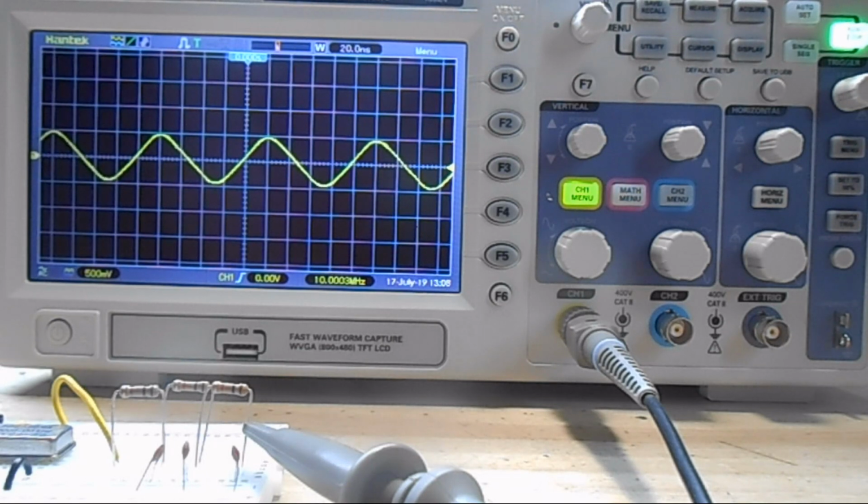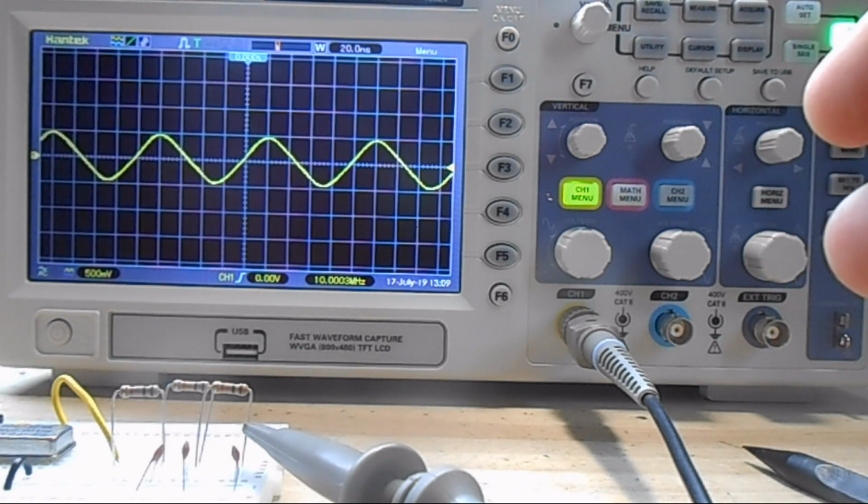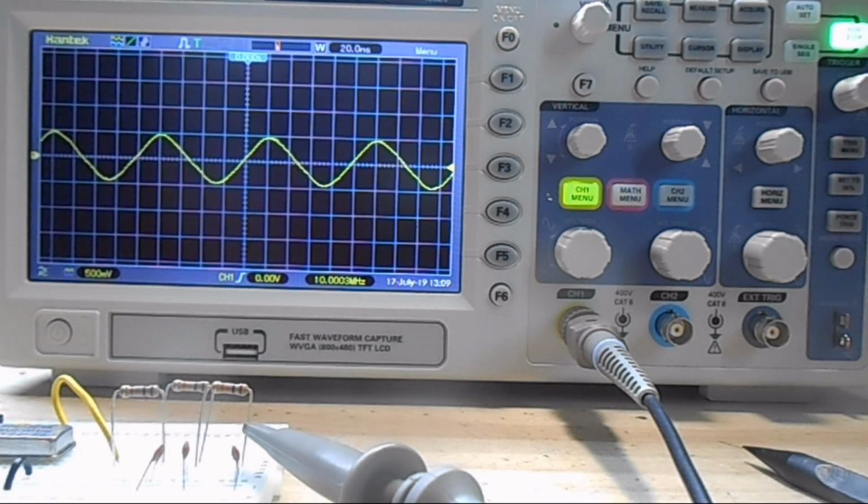Now we also have trigger sweep, and that's what we have over here. You see where we have our run, stop, and our single sequence. We have an auto trigger sweep, which means no matter what, whenever the trigger condition is met, there will be a waveform displayed on the screen. And the data will kind of be frozen before it goes to the next trigger, but you're not going to see that. Then we have normal mode trigger. In this mode, the trigger holds and it displays the last one. And then finally we have a single trigger sweep where nothing is displayed until an edge is detected, and then it shows us one time, and generally our run stop indicator will turn red.